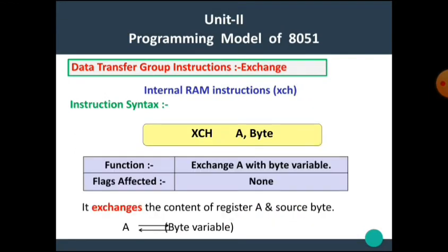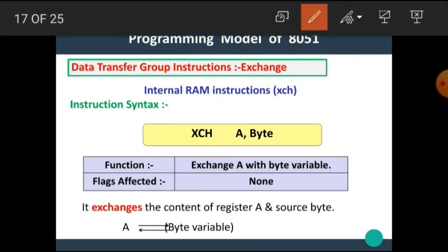Okay, the next internal RAM instruction is the exchange instruction. Its syntax is XCH A, byte. Its function is to exchange the accumulator with a byte variable. It exchanges the content of register A and the source byte.